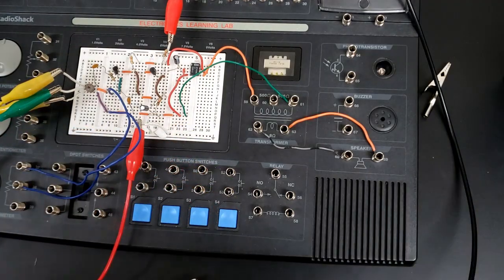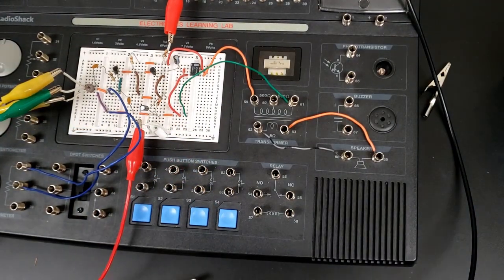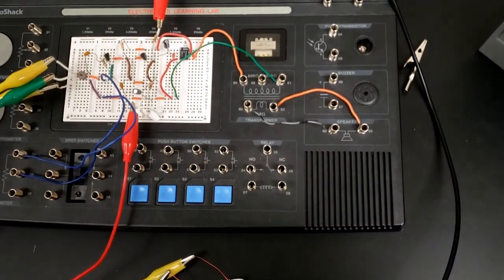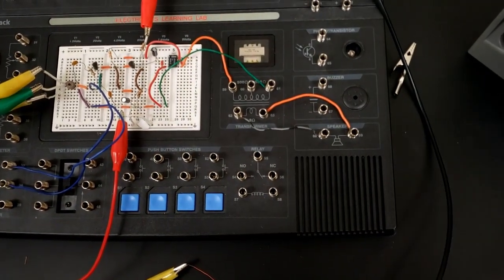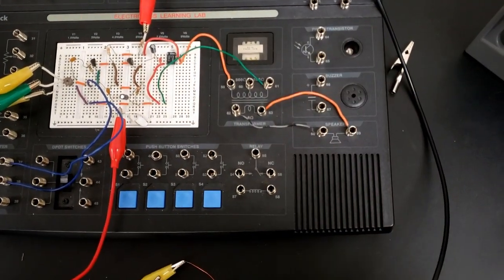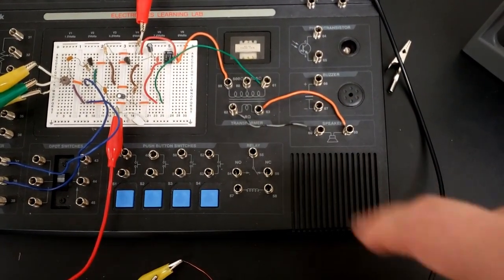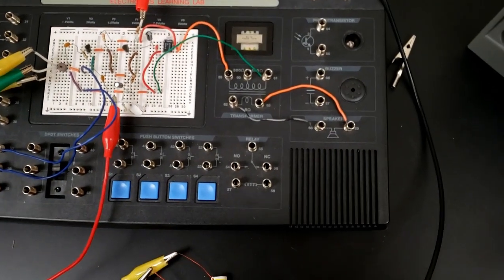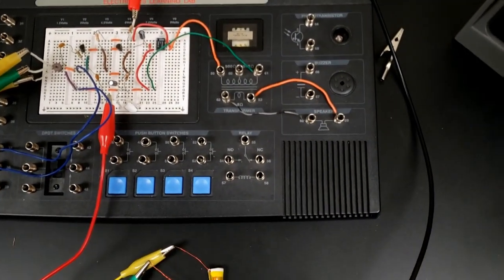We'll go ahead and turn this power off so you can't hear that anymore. But yeah, so we're taking that modulated signal that's coming from this function generator, and then this circuit here is doing the three things that we talked about, which was it's first filtering it, and then it's going to demodulate it, and then it's going to amplify it, and then it's going to output from this speaker. All right, so that's going to be the end of this lab.